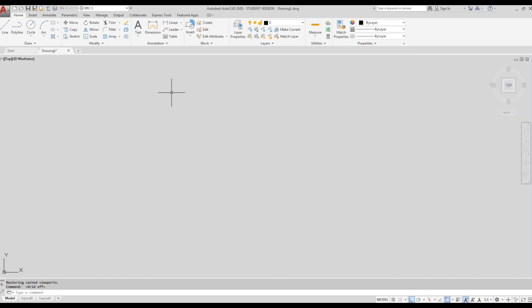geometrical relationship. And last but not least, object snaps, probably one of the most important utilities, because this allows us to ensure that all points are connected at either endpoints, midpoints, centers, quadrants, tangencies. As stated, we will be looking at object snaps quite a bit closer in an upcoming video.